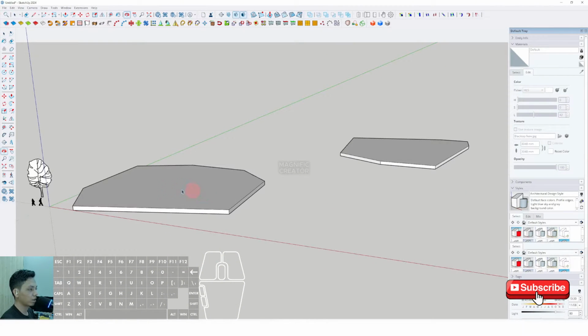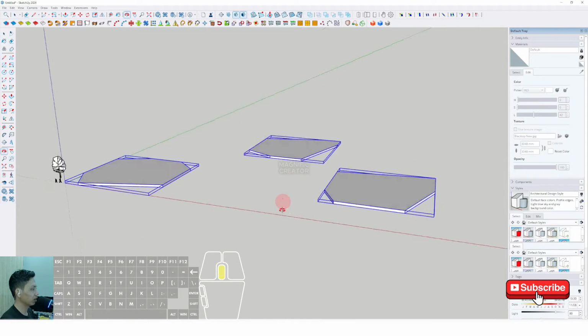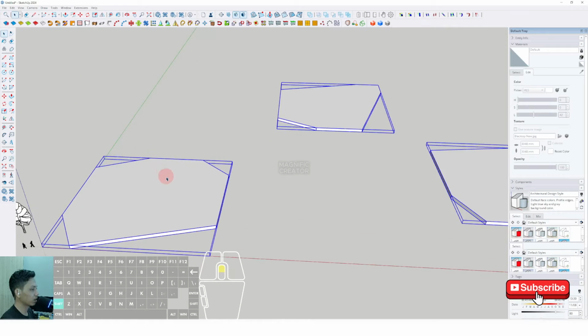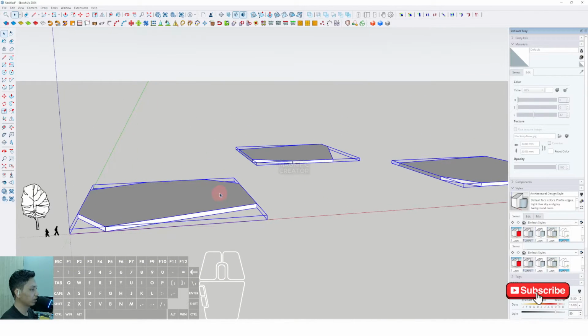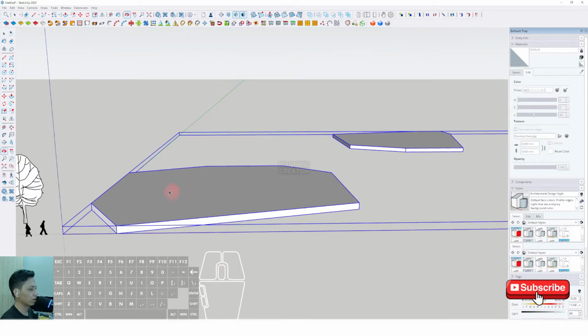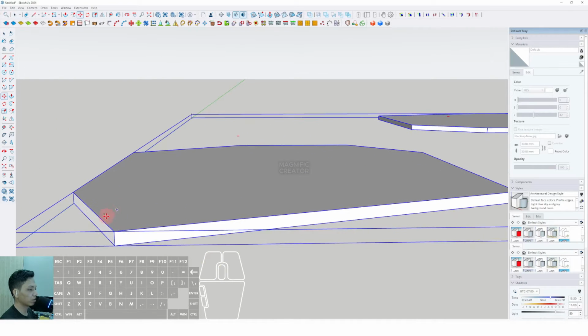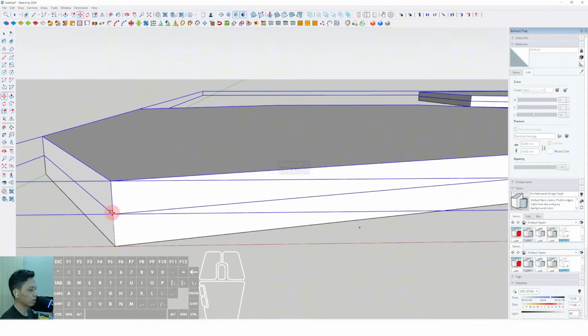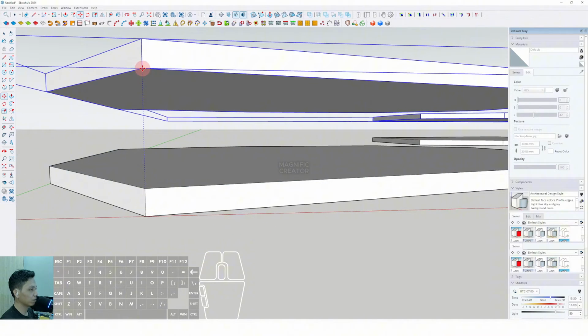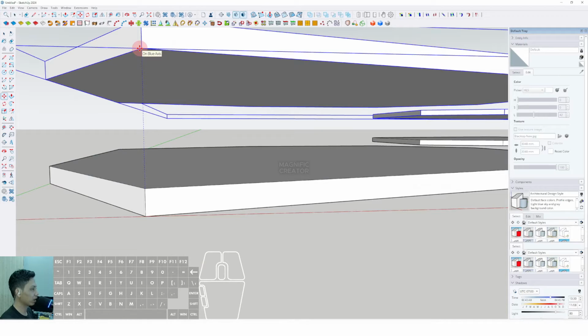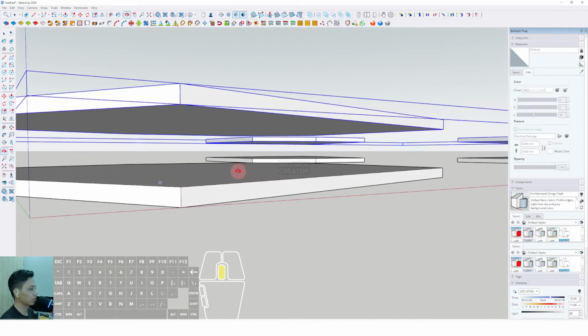Okay, then we can click all of this triple tower like this, and we can also make it a group. Okay, then we can select move, type control, click this position and then place it in this position. Then we can move it up. We can set the floor to ceiling around 4 meters like this. Okay, it's just for example.